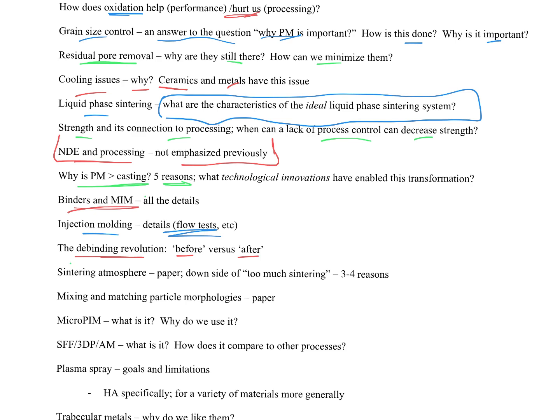Something that we didn't have to think about too much for ceramics, but is very important for metals, is the sintering atmosphere. With ceramics, with the exception of silicon nitride and silicon carbide, which we don't care that much about in this class, you throw things into a furnace in air and you're good. That was fine for the vast majority of oxides. Not so for metals. Not only is it not air, it's also more than one atmosphere. We can start out with a hydrogen-based atmosphere, not 100% hydrogen, but 4%, 5% hydrogen, and then switch over to argon or nitrogen, whatever works for us in terms of properties. So it's a different situation, and it gets into this concept of